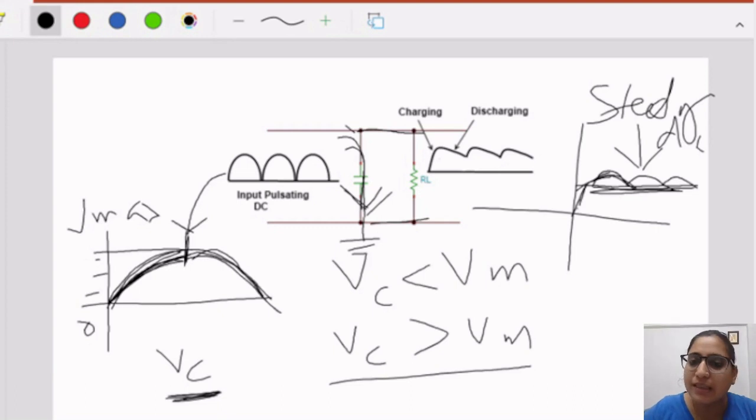When the DC component is coming toward the capacitive filter, it already works as an open circuit. So whatever the input voltage is, it goes towards RL, and the DC level is maintained. The AC components flow towards the capacitor, and the capacitor grounds those components, and the DC component goes to the resistor RL. So this is the whole working of a capacitor filter. Here one thing we have to notice is that XC for the DC component is infinite.